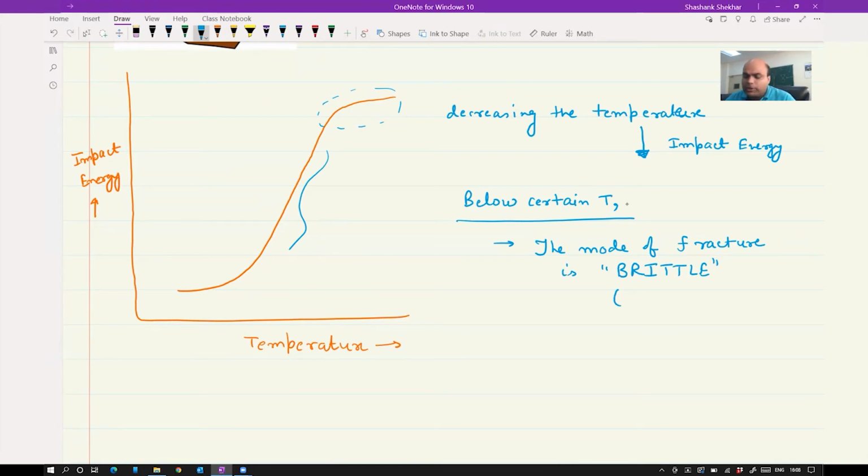and so what we do, we can see now the fracture surface. So you have fractured the surface. Okay, now look at both the fracture surfaces. We have two surfaces, right? Two parts of your sample. Okay, so you look at the fracture surface, and by looking at the fracture surface, one can determine whether it has brittle behavior, or brittle fracture, or ductile fracture, or a combination of brittle and ductile fracture.